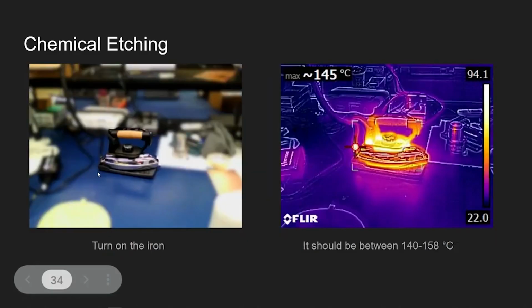After that, an iron was turned on to preheat. Using a thermostat or a FLIR camera, iron temperature can be checked and it should be between 140 and 158 degrees Celsius. The temperature does not need to be exact. Attempt the process at the middle range temperature, and if it doesn't work, then make the iron hotter.